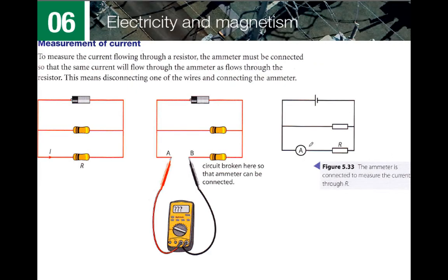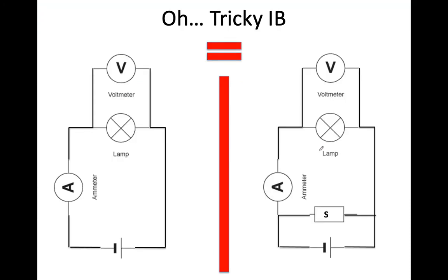An ammeter, on the other hand, is in the circuit. And the reason that an ammeter is in a circuit is because what do amps measure? Amps measure the flow. So if we want to measure the flow of something, it has an infinitely low resistance. The reason is we want it to be part of the circuit. We want to measure how much is flowing through here, but we don't want to interrupt that flow and change the flow. All right.